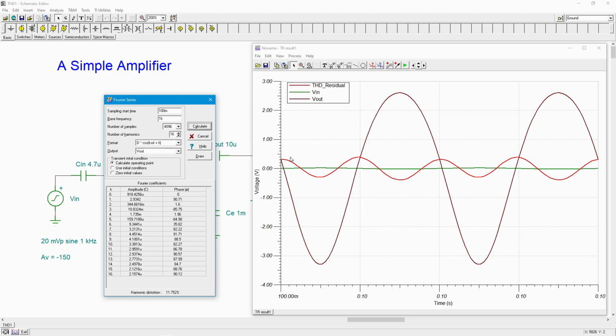Okay, so here's your cosine. See how it's starting up here? And it's coming along at twice the frequency. And if we actually check these amplitudes, we got some different numbers because this is really the total residual, but we were getting 300-ish, a little over 300 as we were going through here, all depending on which peak we were looking at, right? So this is saying, well, the actual second harmonic is roughly 345 millivolts.